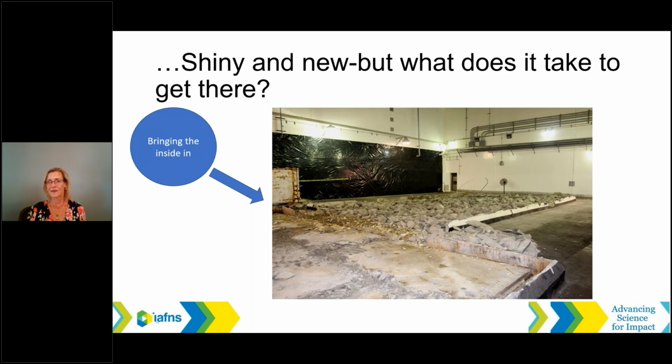Then the removal of the concrete pad, which entailed jackhammering the concrete. As you can imagine, the concrete dust was significant, and the Listeria was heavily contained within the pad. And they managed the project by constructing a temporary wall, which is the black structure in the back. There's a production room immediately behind that temporary wall. They hermetically sealed that wall so that no dust could get in back of it.